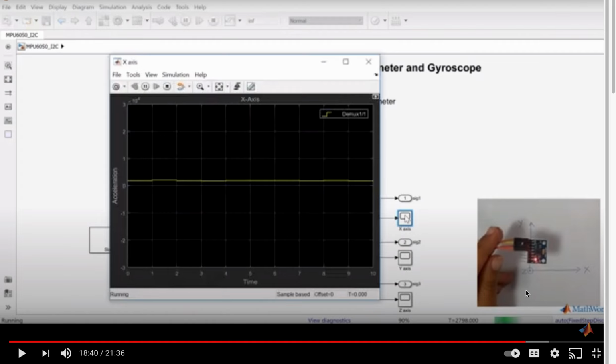So right now, the only component of the acceleration sensor that can pick this up is the z component. So if she starts dealing with the x, you're going to get 0. Not until she turns that x-axis and flips this printed circuit board vertically up so it points into the z direction will you get gravity.